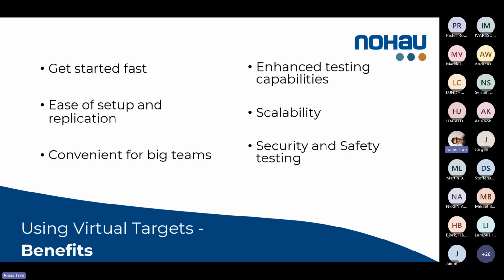So while there are advantages to using virtual targets, they should not be considered a complete replacement for a real physical target. What some teams do is use a combination of both real hardware and virtual targets. Virtual targets are often preferred during early development and testing stages, and later they migrate the software to the hardware, and they still have to debug the real hardware to validate behavior in real-world conditions.